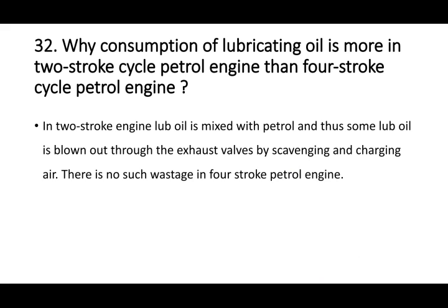Next question. Why is consumption of lubricating oil more in two-stroke cycle petrol engine than four-stroke cycle petrol engine? So earlier there were two-stroke engines. Nowadays the two-stroke engines are banned, and you can find the four-stroke engine everywhere in bikes and mopeds also. So in two-stroke engine, lubricating oil is mixed with the petrol, and thus some lubricating oil is blown out through the exhaust port by scavenging and charging air. There is no such wastage in four-stroke petrol engine. So in four-stroke engine, we do not add oil with the petrol. Okay, so that is why the consumption of oil is more in case of two-stroke engine.